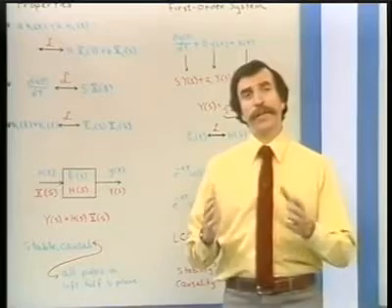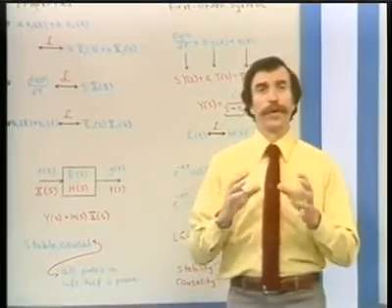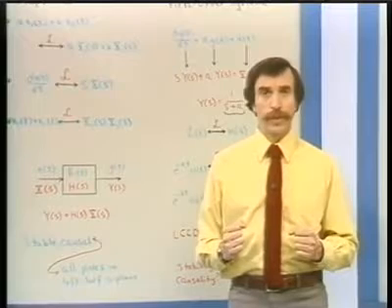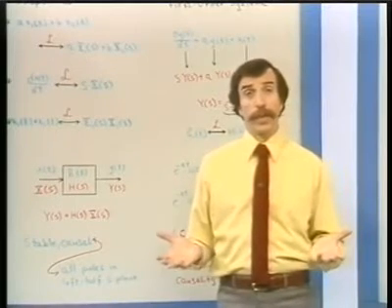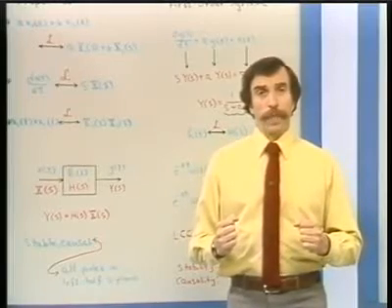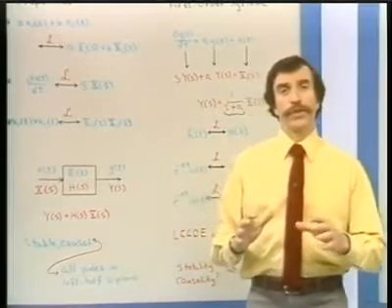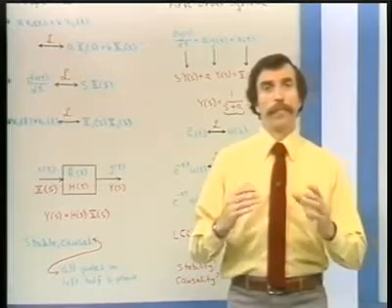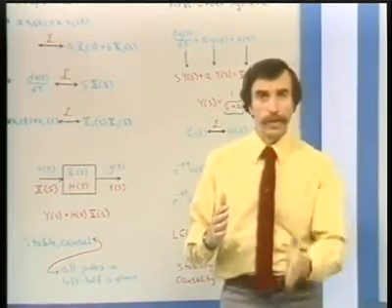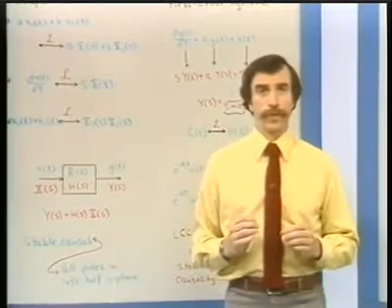And that, in fact, is the same condition for convergence of the Fourier transform of the impulse response. What that says, really, is that if a system is stable, then the region of convergence of the system function must include the j omega axis, which, of course, is where the Laplace transform reduces to the Fourier transform.